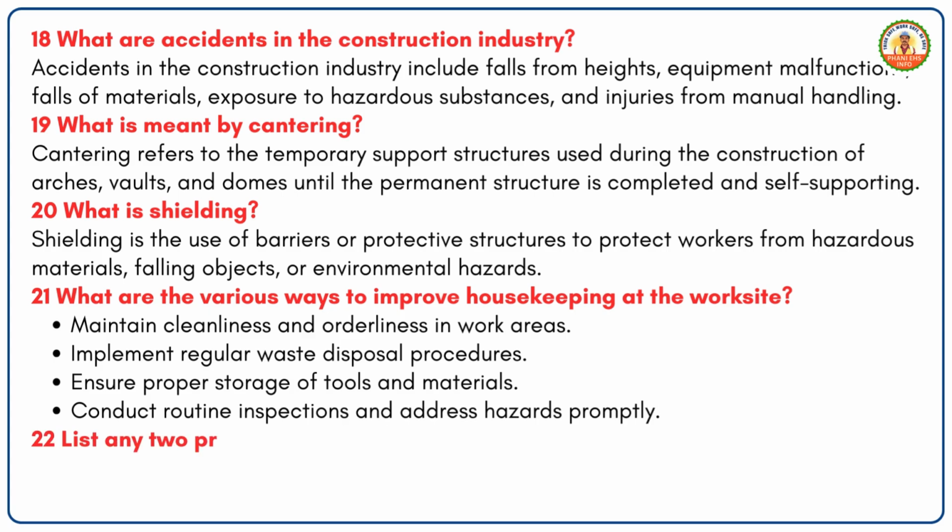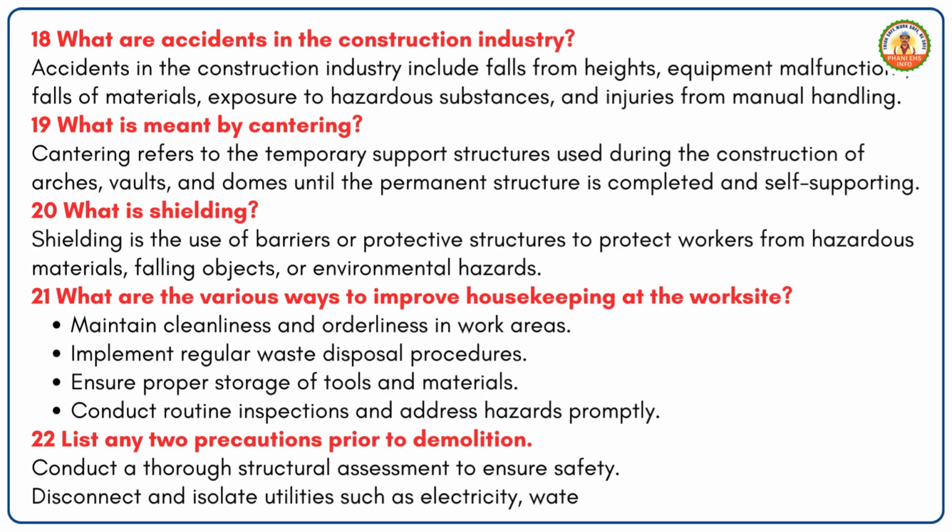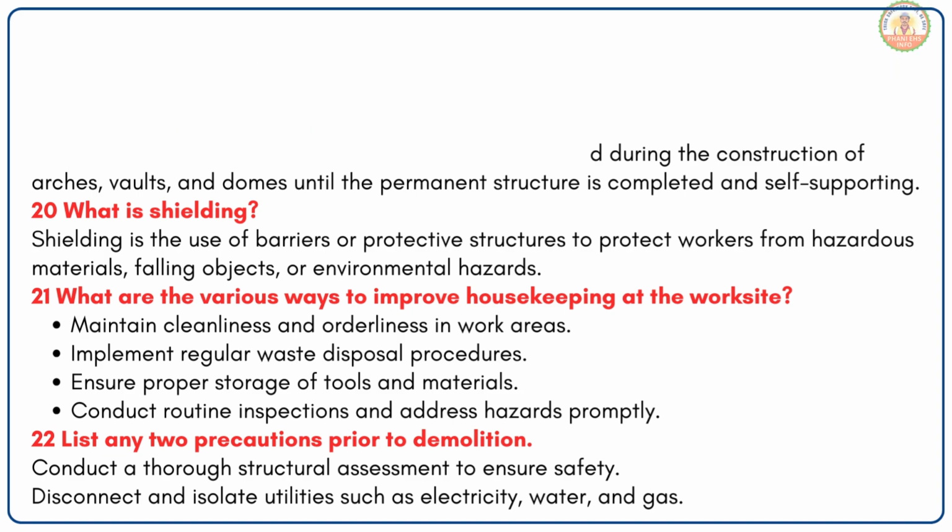22. List any two precautions prior to demolition. Conduct a thorough structural assessment to ensure safety. Disconnect and isolate utilities such as electricity, water, and gas.